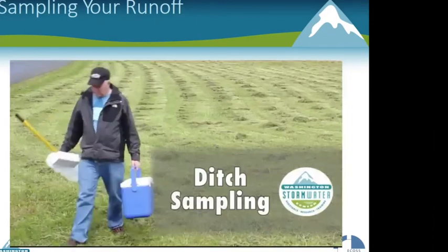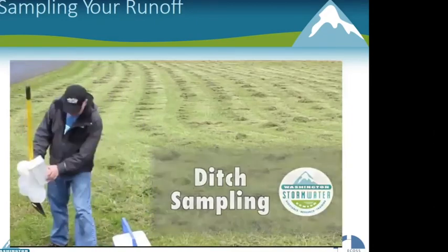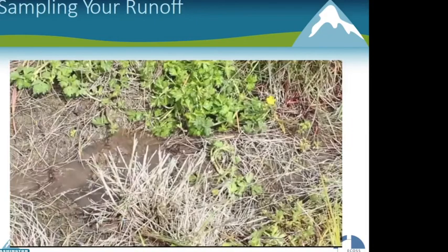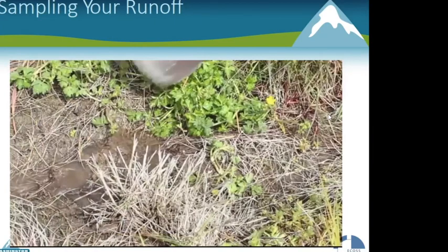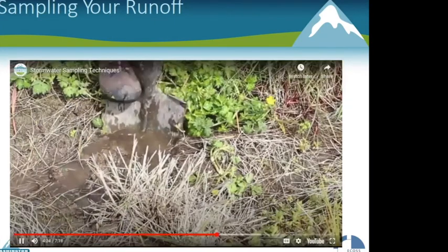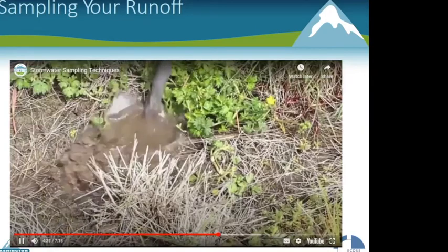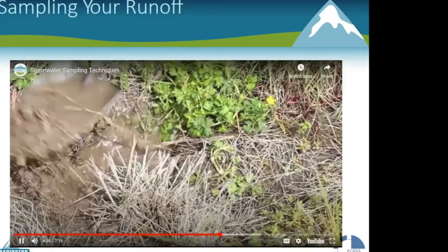If your stormwater leaves your site through a ditch, you can sample there. Make sure the stormwater is only from your facility and does not mix with other stormwater from upstream. If the ditch is too shallow for the sample bottle, you can prepare a location by deepening it.